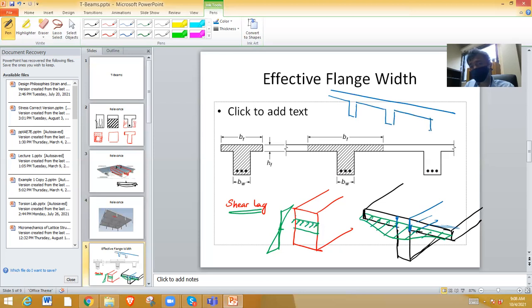You have a long continuous set of T beams like that. Now, if these two are very far away from this beam, then you can imagine, as an intuitive way, that this stiffness is much higher. If you distribute the load in the ratio of the stiffnesses, it is a loose way to imagine, then most of the stresses will go to the stiffer part. So if you think in that way, you can justify this kind of distribution.